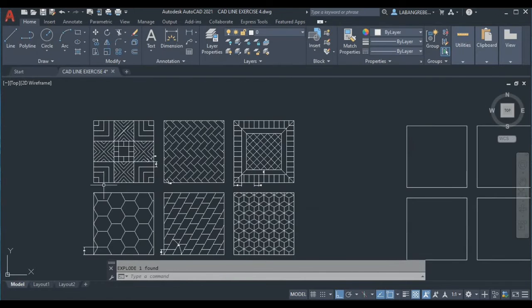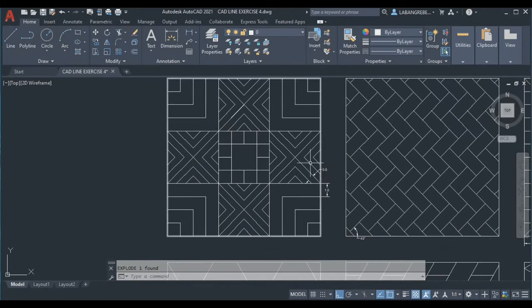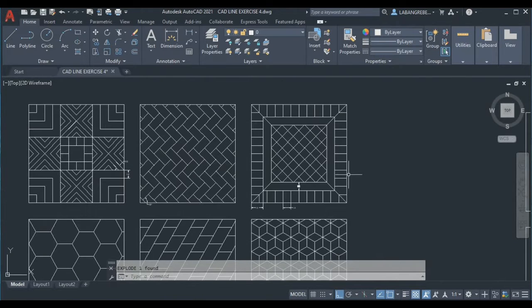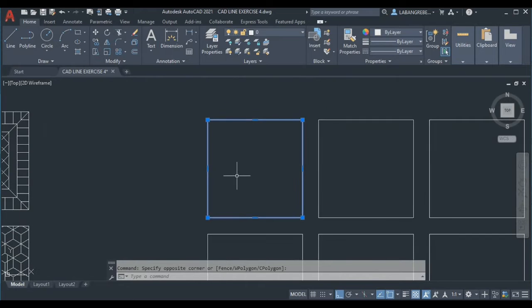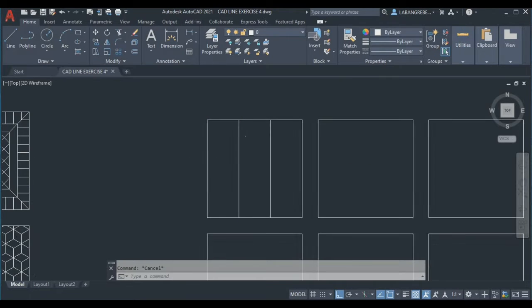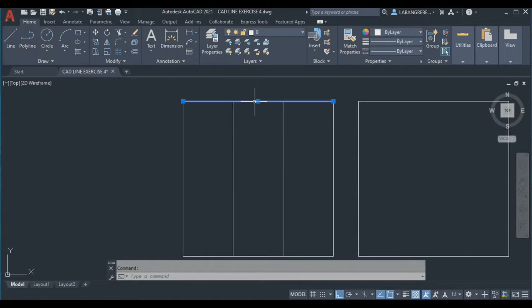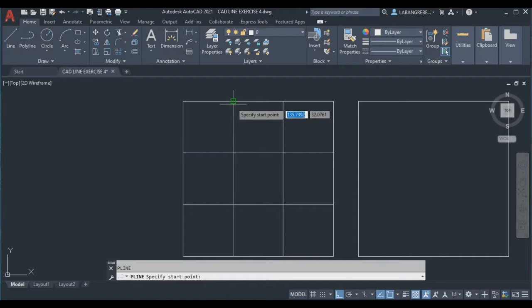Okay, for the first box, if you can see, there is some polyline here again, and then here offset 1, and here 0.5. So first we're going to explode the box, and then we'll offset it by 4, because the distance to each other is 4. And after that, we're going to offset it again by 4 here and here. Then, using the polyline, you can create a polyline from here to here, and then select that line, then offset it by 1.